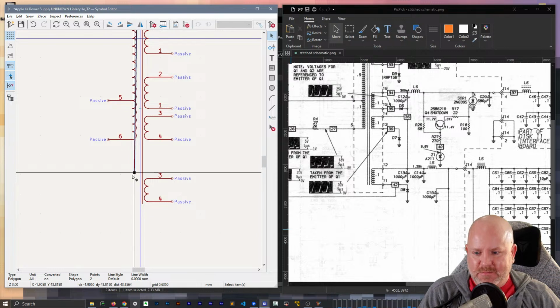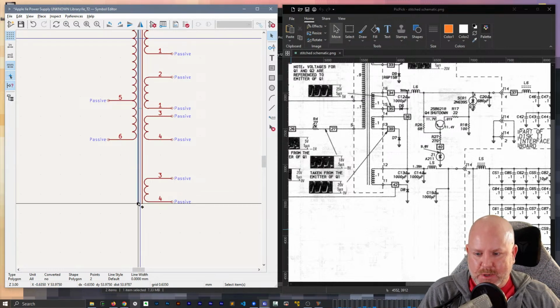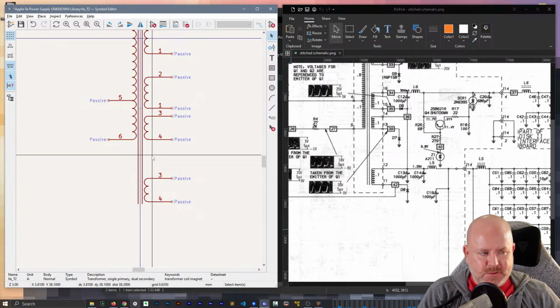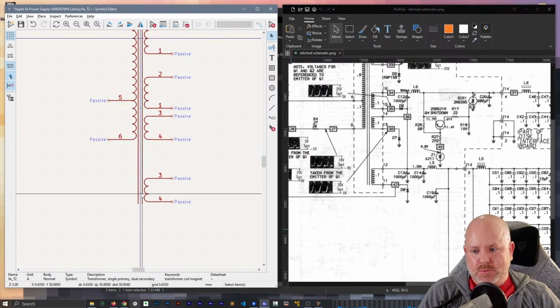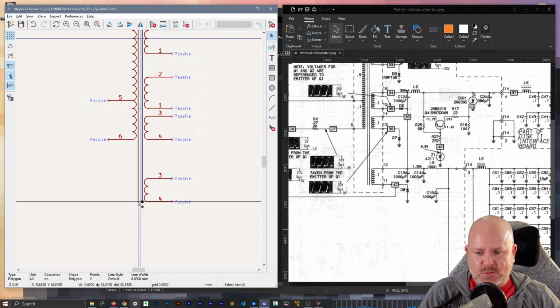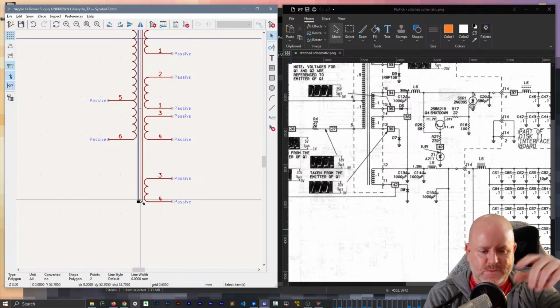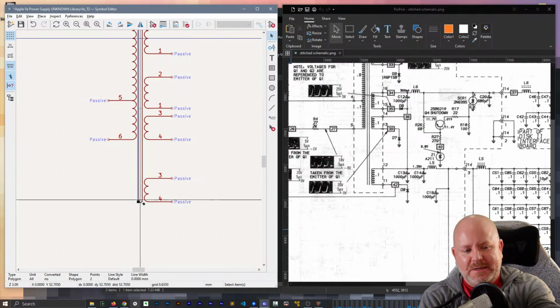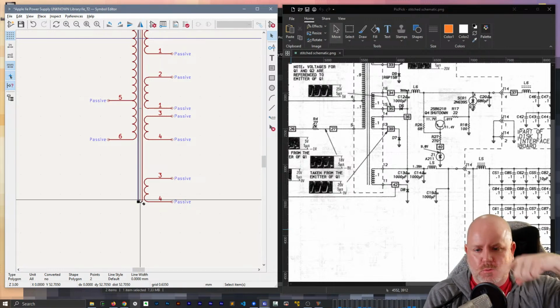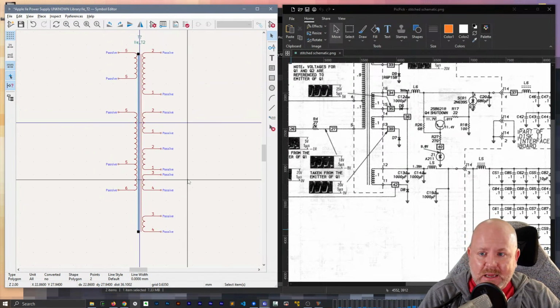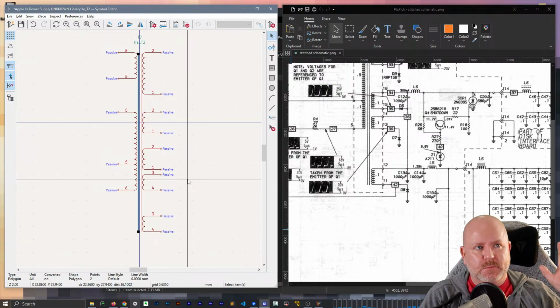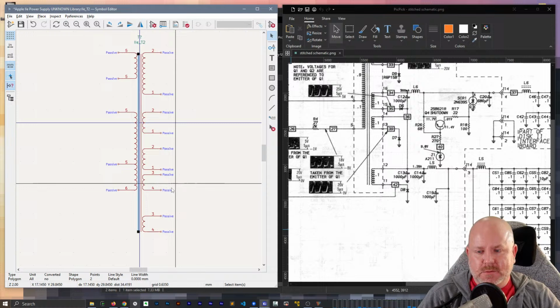For the footprint, like I said, especially if it's a standard pin spacing, you can just use an existing pin header or pin socket footprint, and at most add a silkscreen box around the module, and that way on your circuit board you would know where the space would go. But yeah, if you're trying to make a board that combines a couple of modules together, then I do think that's actually a good first project for KiCad.